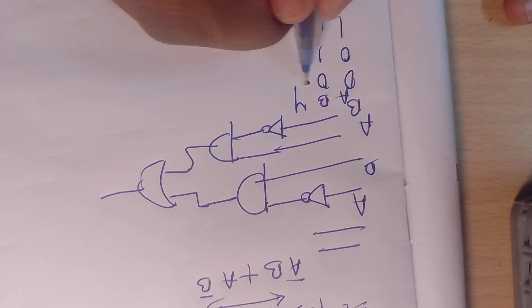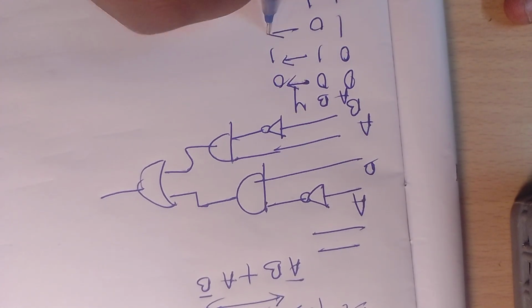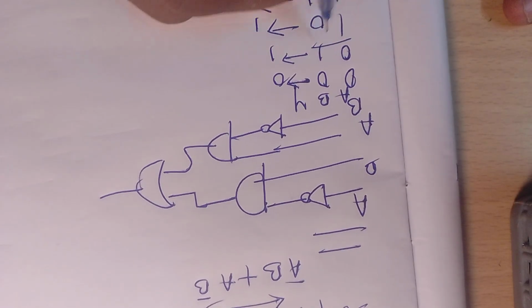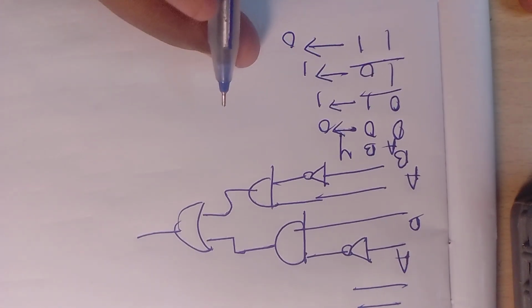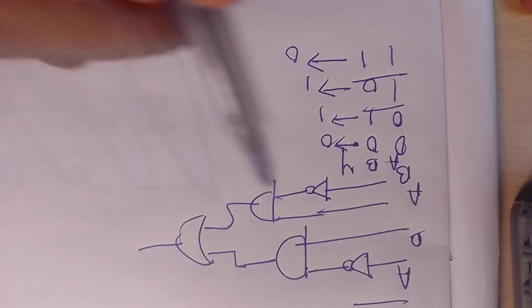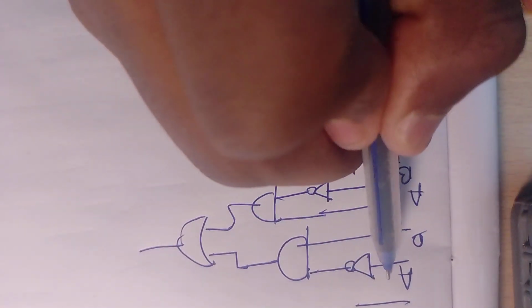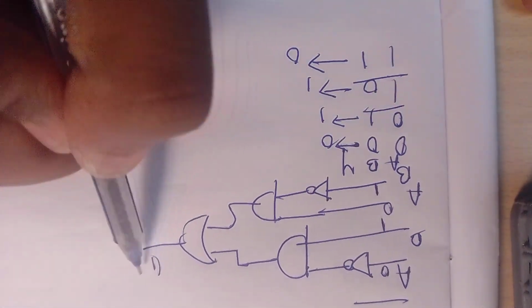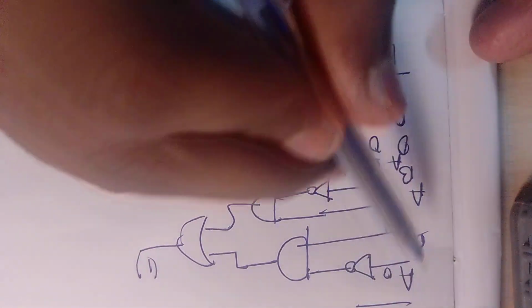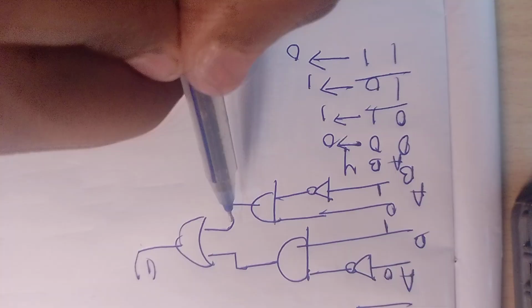Now what is going to happen, it is going to be an odd one detector. Whenever there is an odd number of ones, the output is going to be 1. So that is nothing but an odd one detector. Now you can apply input over here. For example, I will apply 0 and 1, 0 1. You can see the output has to be 1 whenever you apply some input. It depends upon the present inputs only.